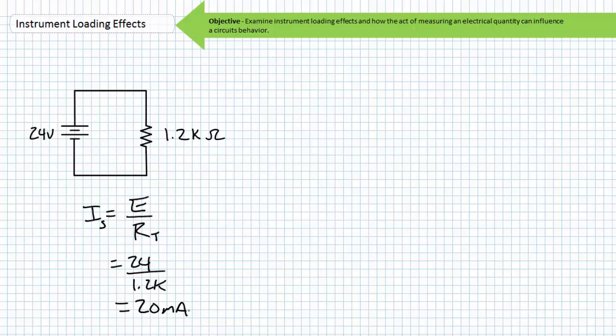For our level of detail, we do not care about things that only minutely affect reality. Ohm's law states that the current through a 1.2 kilo ohm resistor with a 24 volt drop across it should be 20 milliamperes. When an ammeter reads approximately 19.92 milliamperes of current, I'm cool with the fact that there's a small error. A difference of 0.08 milliamps isn't worth a second glance.